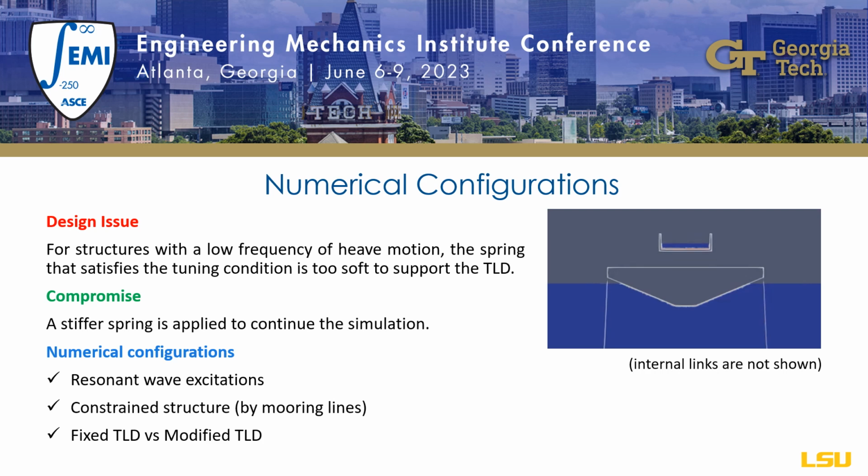However, we ran up against some unforeseen issue when designing the internal spring dashpot system. The problem is that the heave frequency of the floating body is very low, so the spring has to be extremely soft to satisfy the tuning condition, while it is unable to support the liquid damper.